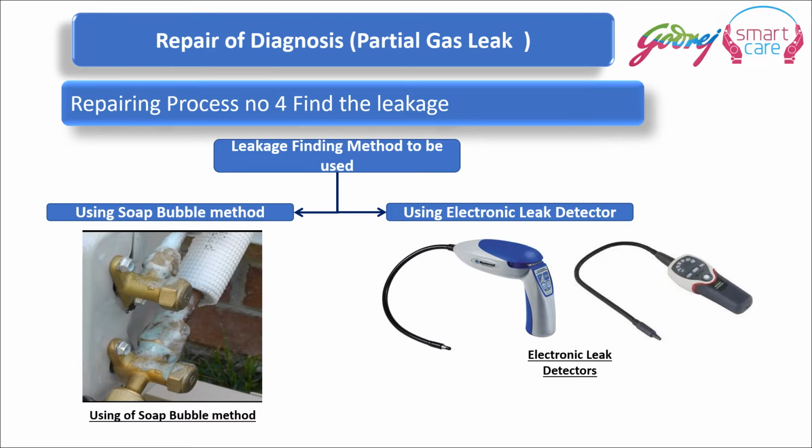How to find the leakages? That is through a soap and bubble method. We wet some soap onto a sponge and then make a lot of bubbles from it, and these bubbles have to be applied on each and every joint, and when there is some kind of bubbling which is automatically taking place from that joint, that will indicate that the leaking gas is producing more bubbles in that soap. That is the way how we check the leakages from the joints.